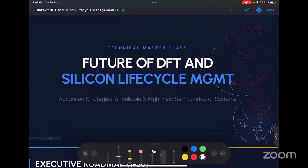RTL design, and then in between synthesis, and this is the section where DFT logic is getting added to the design, the actual functional design. And with respect to that, the entire DFT logic goes through place and route and the STA and all those ASIC domains.